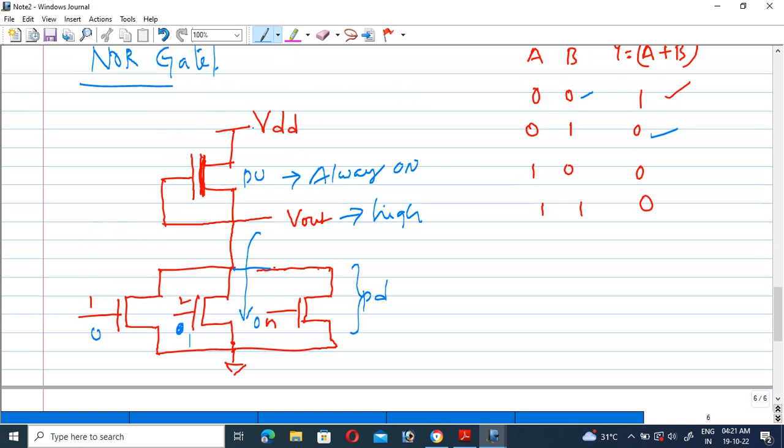We know that generally this is a ratio, right? This pull up network size cannot be affected by this pull down network, because in the case of a parallel network, the resistance value is always the same. That means all the pull down network nMOS transistors have equal resistance value, the same impedance value. So if you want to maintain the 4:1 ratio, obviously it is possible. That is why the number of inputs in the case of the NOR gate cannot affect the ratio of the corresponding network. Therefore, the size of the device is also very reasonable.